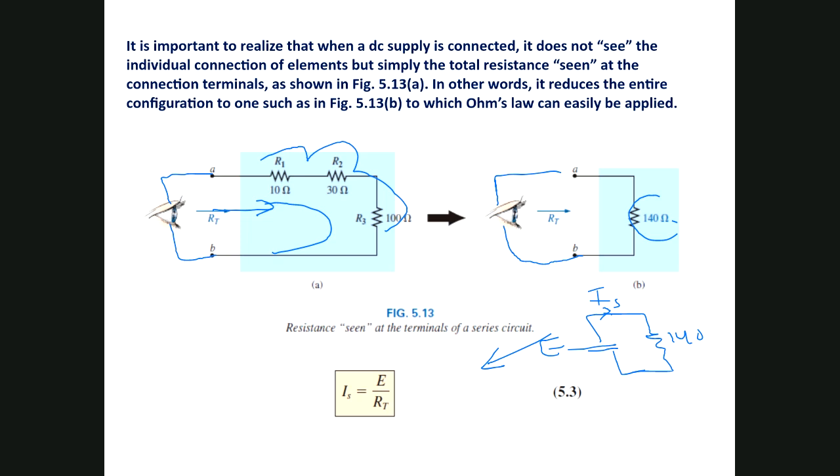It becomes clearer when we deal with a complicated circuit. When we go through simplification, then we can find the currents, the voltage drop, and so on. Just remember now this note: you will apply the simplification from the side opposite of the source.